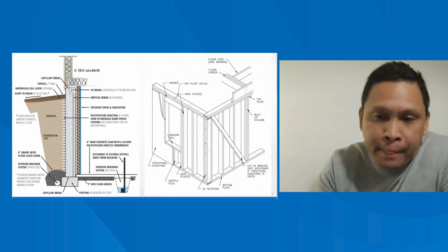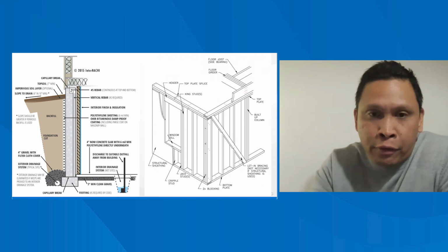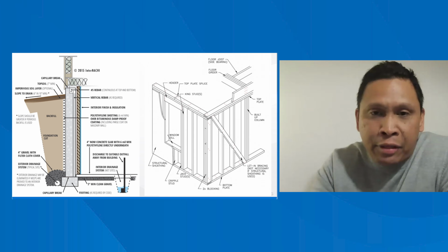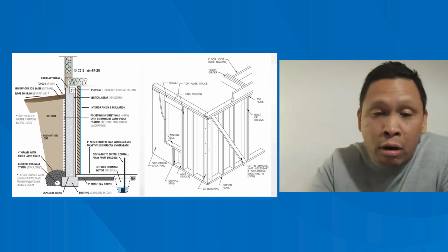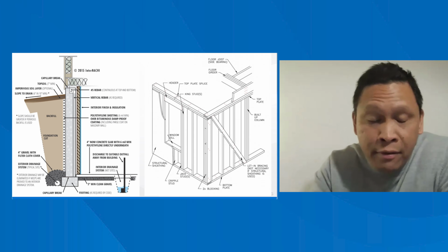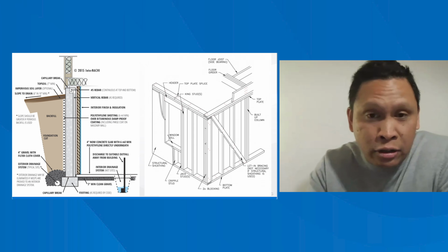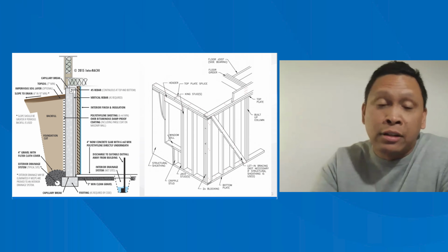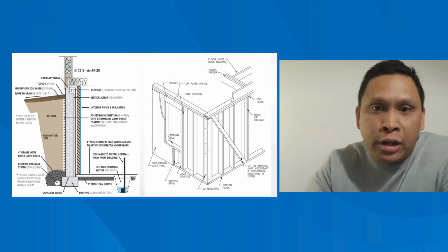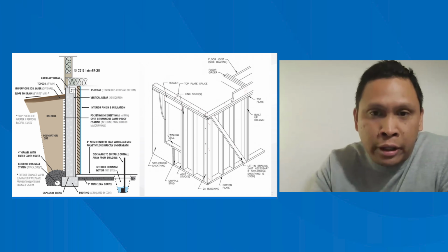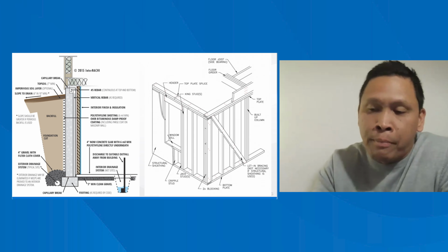So it's important for those of you that do have the opportunity to get out there and take a look at the foundation before they backfill it. You will find oftentimes that the foundation system will have additional areas where they could actually stand to apply more damp proofing. And sometimes you'll find that there is bare concrete, not actually covered in damp proofing, that could absolutely absorb the water and over time transition into the home.